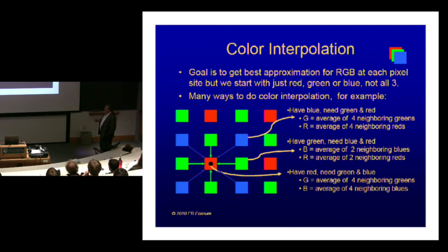And just as you might imagine, we don't know what green is, but our next best guess is we'll take the average of the 4 surrounding greens and pretend that's our green color, and the surrounding 4 blues will be the blue value for that pixel. Works great most of the time, as long as the colors are not varying quickly across the pixel array. If you have a sharp edge, then you're going to have an aliasing problem. This relates to sampling theory in a lot of different fields. If you're sampling at too low a frequency, you're going to miss sharp edge transitions, and you're going to get some weird effects.